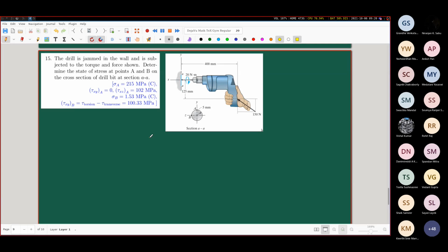Depending on the situation, you may also have to try maybe one force balance and two moment balances. So keep an open mind about it. Of course, in this particular problem, it will be enough for us to consider the very standard set of equations: sigma Fx equal to 0, sigma Fy equal to 0, and sigma Mz equal to 0. Okay, so we'll do that.